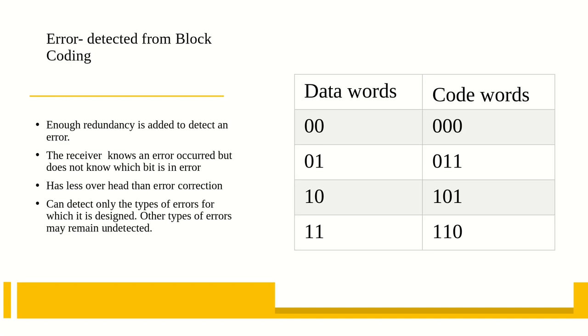The receiver receives 011. It is a valid code word. The receiver extracts the data word 01 from it. So it is correct. The code word is corrupted during transmission and 111 is received. This is not a valid code word and it is discarded. The code word is corrupted during transmission and it gets 000 at the receiver. This is a valid code word. The receiver incorrectly extracts the data word 00. Two corrupted bits have made the error undetectable.